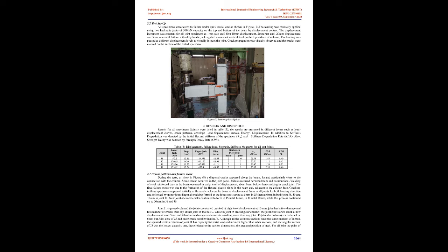The experimental portion of the investigation consisted of testing 4 beam column joint specimens. The beams were cantilever supported and had a clear span of 700 mm. The columns were variable in shape, but they have the same moment of inertia about the x and y axis. Figure 4 shows the used reinforcement cages and formworks. 6 electrical strain gauges were fixed to the vertical and horizontal steel bars and stirrups before casting of concrete for every single joint, as shown in Figure 5.